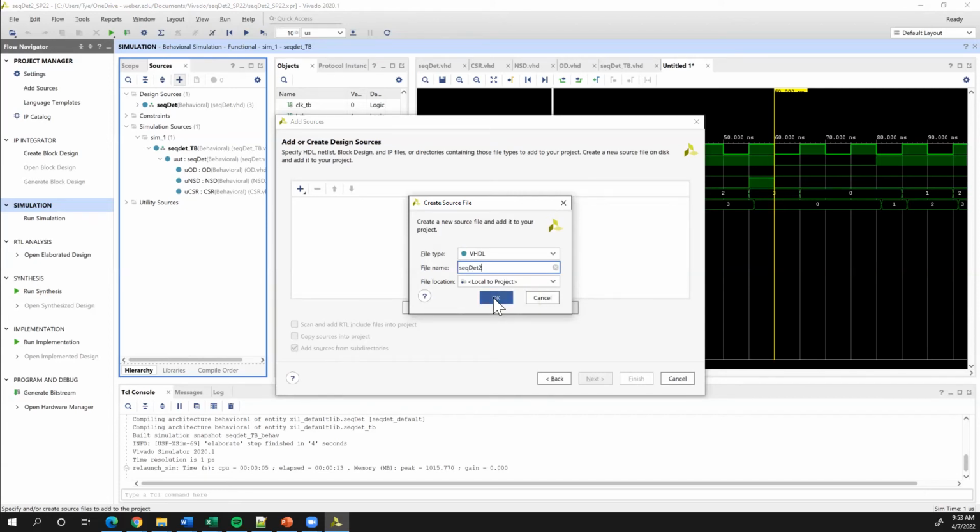S1 is the state where you've seen 1, 1. Yeah, because state 0 is I haven't seen any ones yet. I see 1, 1, I come to state 1. State 2 is I've seen at least 2 ones. So why did it go to state 2? A second 1, a third 1 stays put. So this is any number of ones greater than 1. I've seen 1, 1, or I've seen a 0. I've seen 2 or more ones. I've seen a string of 1s and then a 0.